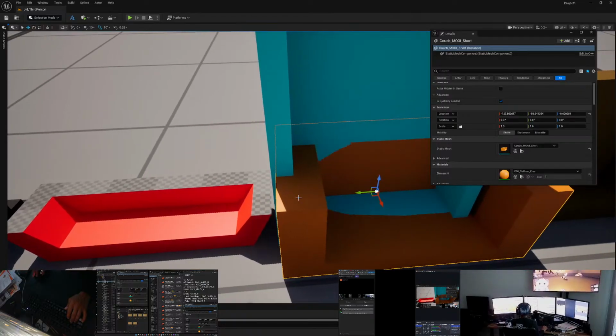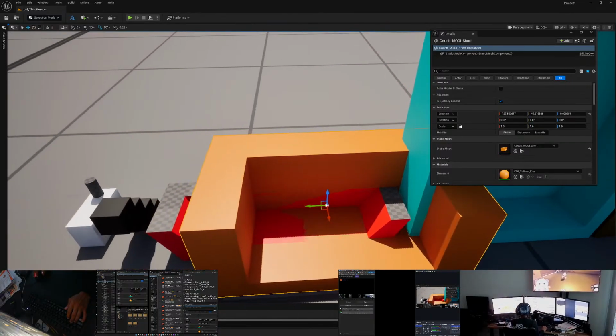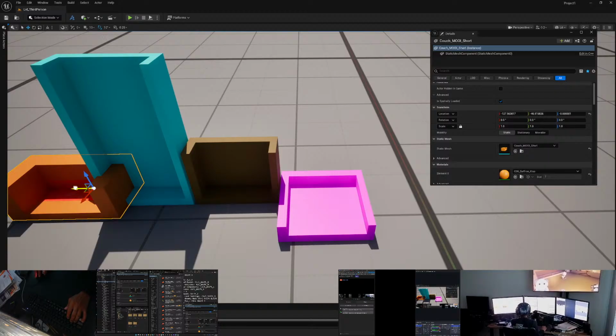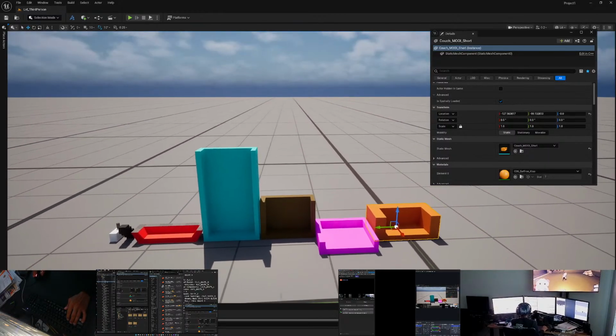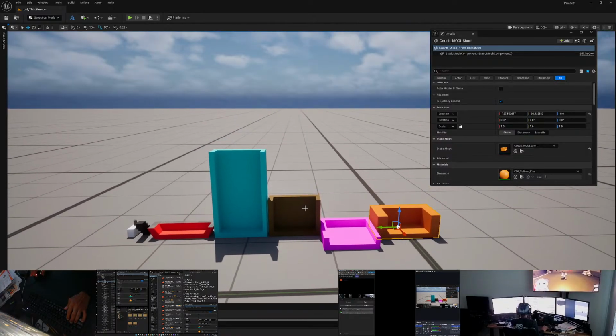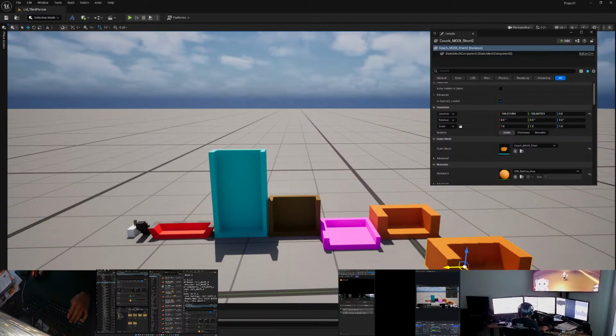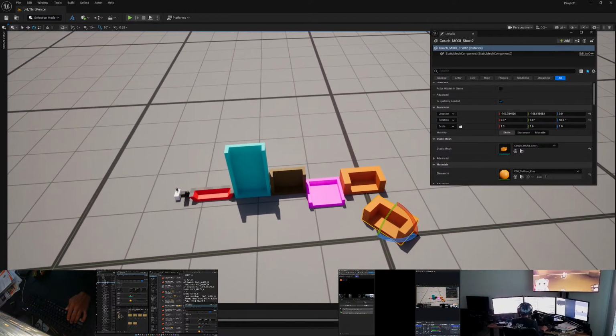So I think about how to adjust the axes in SketchUp for each component and each group. And that gives me a variety of assets that I can now work with to populate my scene. And then all I have to do is Alt and drag this around and orient it how I want, to now have duplicates of that.